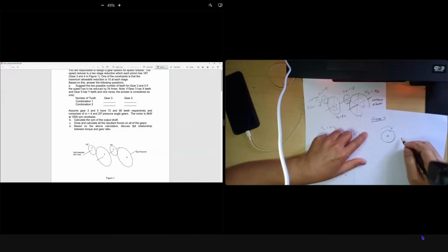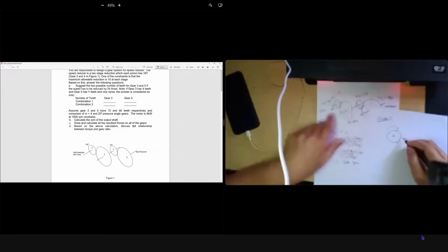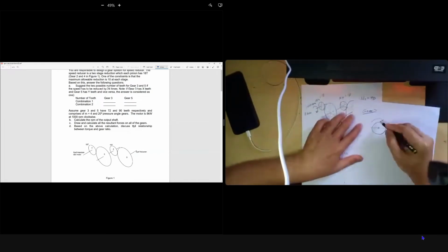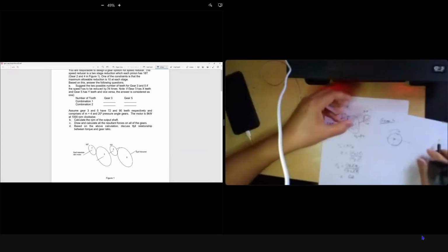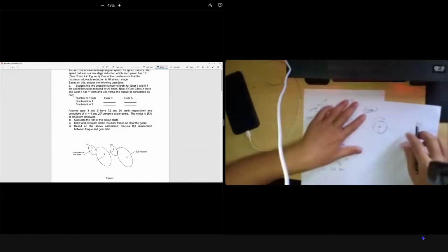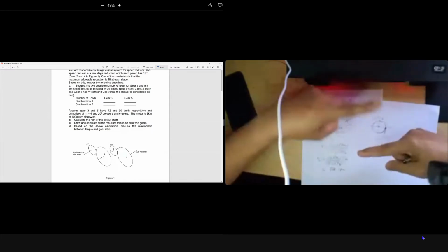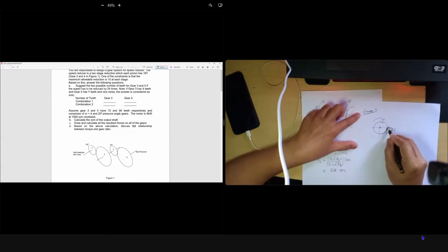And what is the reaction on gear 2? F tangent, okay, because gear 3 is on your right of gear 2. So this will be your gear 2. Is the force F tangent downward or upward? Gear 2 is driving. Yeah, upward. Don't be confused. Upward, because gear 2 is driving. The teeth of gear 2 is touching. So F tangent 3 to 2. F radius is always toward the center. F radius 3 to 2.